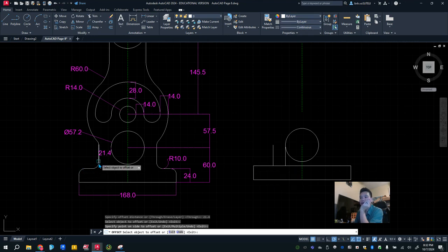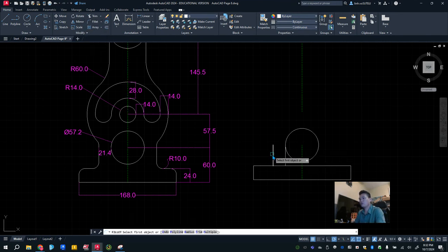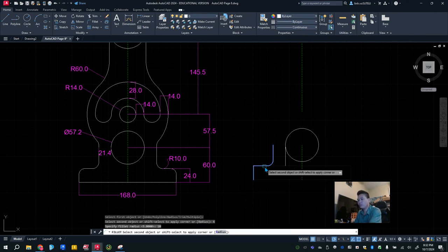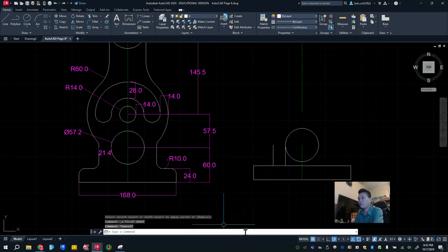All right, so when I have that, let me see here. There's a little arc right here that's radius of 10, so I'm going to do fillet. First object, click on radius, put in 10, hit second object. All right, that gotta get rid of my thing. So what I'm going to do first is trim one of these little things.